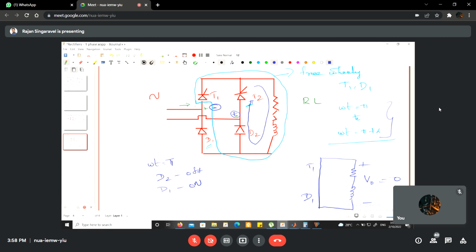Depending upon the load nature, if your load is to be subjected only to the first quadrant, then we can prefer the semi-converter. The reason is that instead of two thyristors, you can use a diode, where you don't need any gate triggering circuit, no need to generate pulses. So a certain amount of cost is reduced, and complication is also reduced.